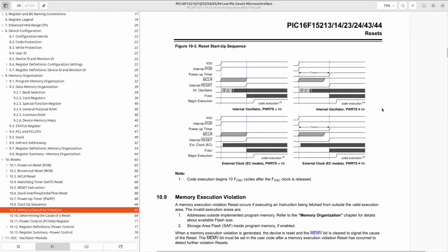So how long do we actually hold it low? Well, for that, I had to look up how long the startup takes for this microcontroller, and it really wasn't all that helpful. It gives us these graphs, but not any values to go along with it. Except that it kinda does. See, I couldn't figure out under normal circumstances how long it takes for the microcontroller to start up, but I did discover that there is a way to define the startup time.